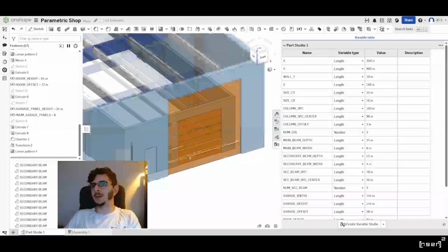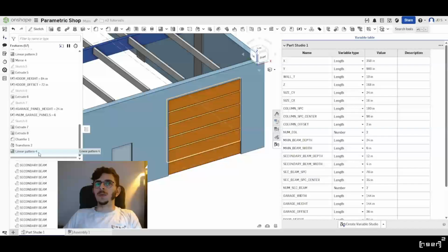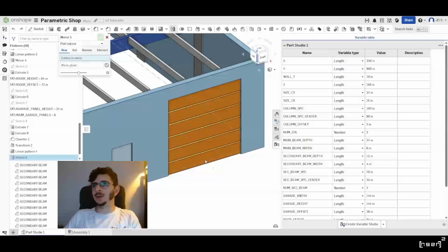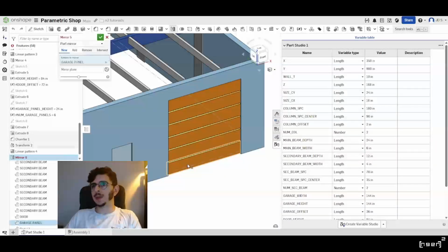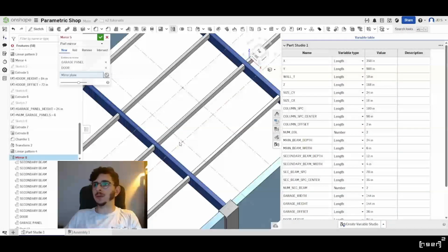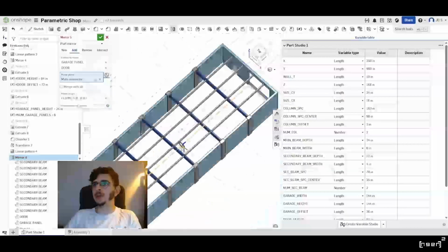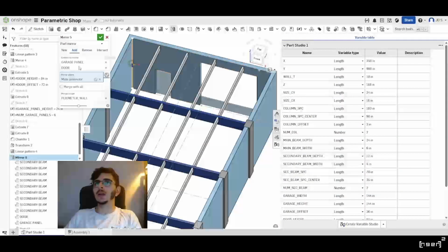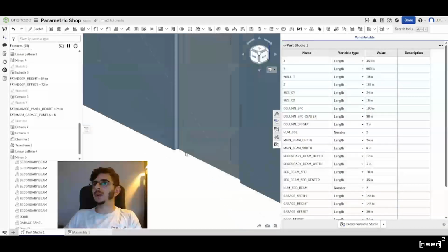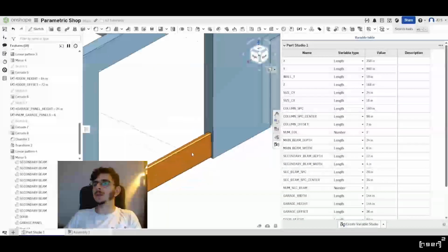separate link or something. So we don't want to mirror all of these because the number changes. What we want to do is mirror the bottom one only, and we'll use this non-changing reference as the mirror plane. Go new here. So we got that nice symmetry right there.